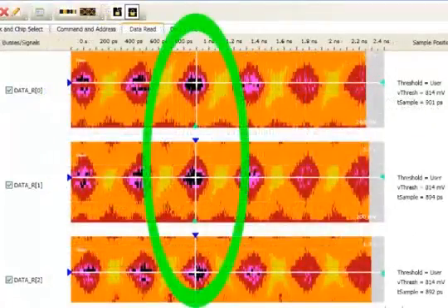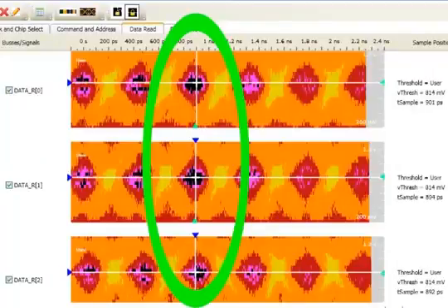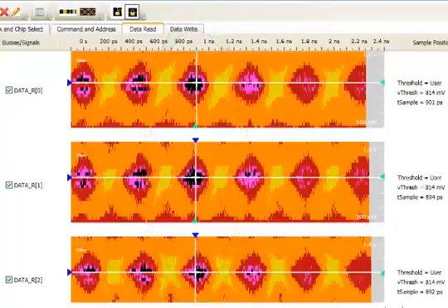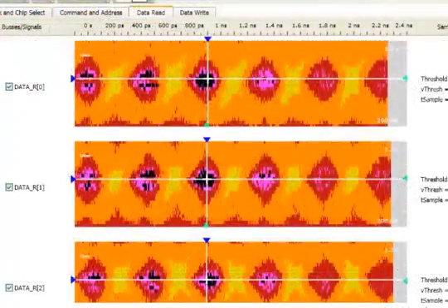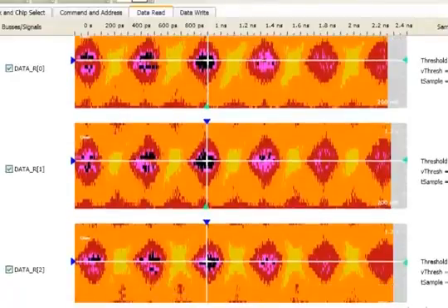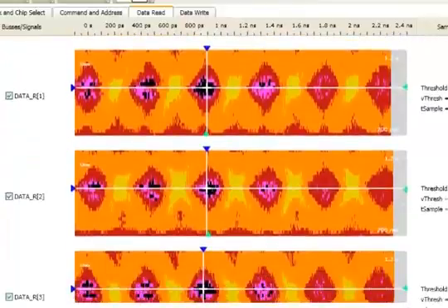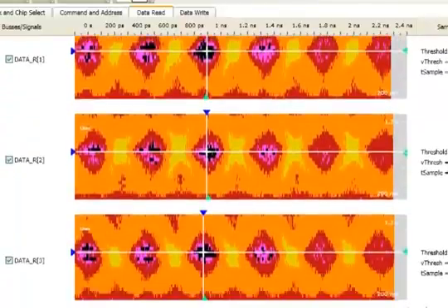One of the first things you'll notice is that these eyes look relatively small. And that's true. At DDR3 2340, the eyes captured from an interposer are very small. The U4154A is the only logic analyzer capable of capturing any DDR3 data from any probing over 1867. The power of bus-level signal integrity insight is being able to scroll through all of the signals in a group relative to each other and to identify signals that need to be addressed with a scope.